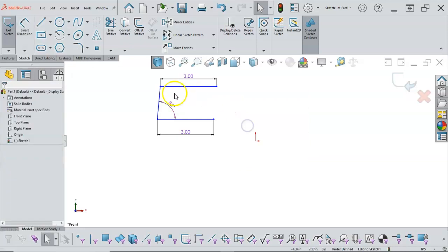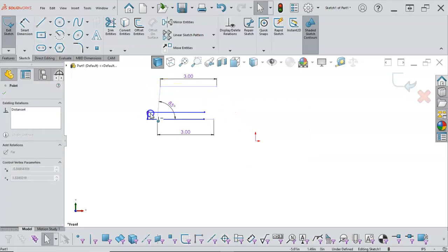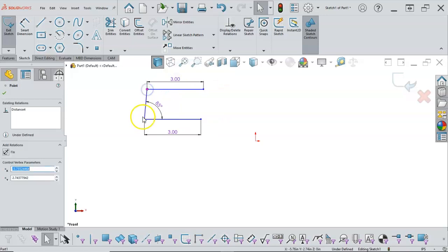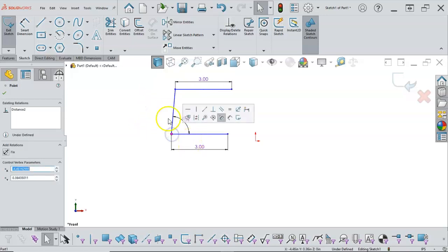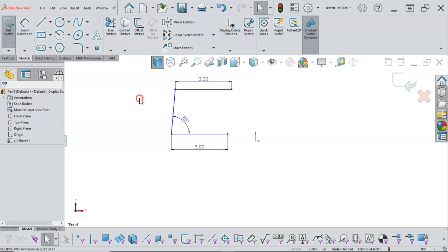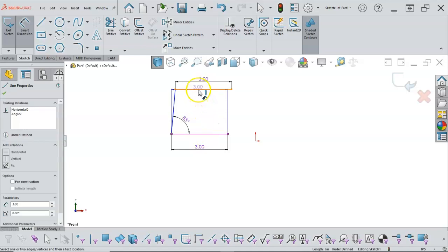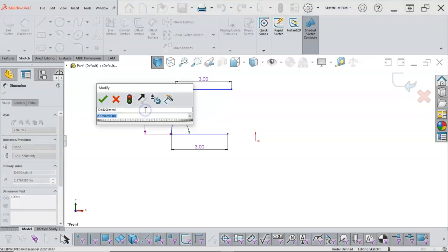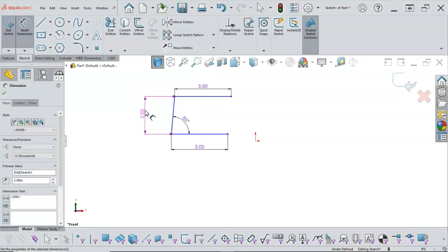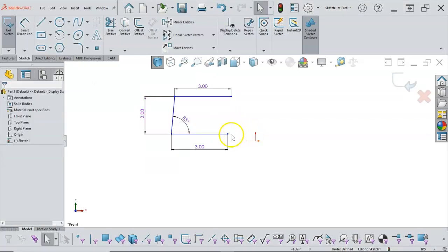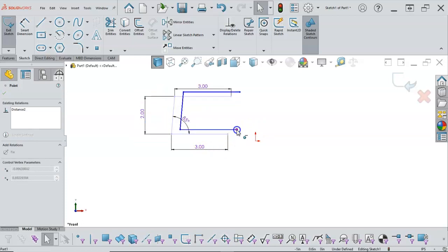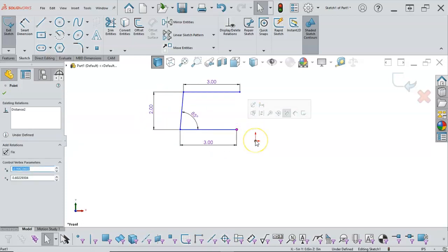All right, so as it sets, then this is by grabbing an endpoint. This is going to be my first debug tool, is to move it around, just observe how it's reacting to being dragged around the screen, and then we'll go between the two and make that 2 inches, and then it's still able to move because everything's in blue and I haven't tied it to the origin.